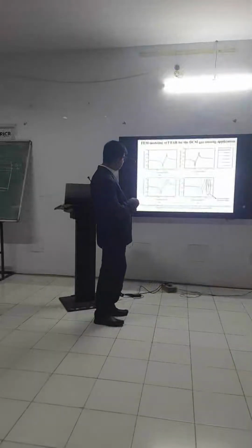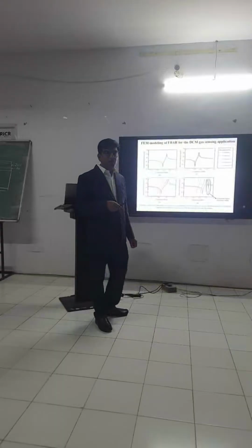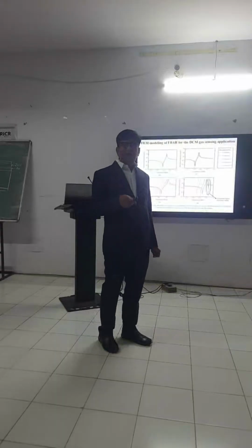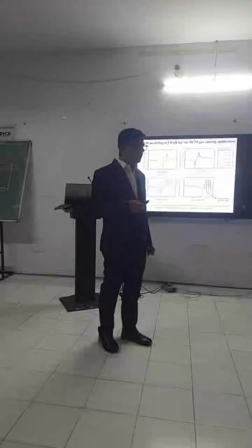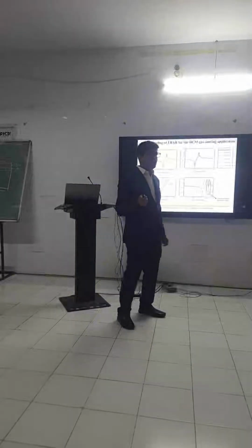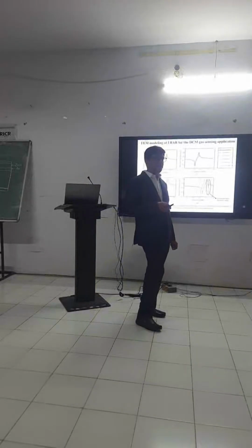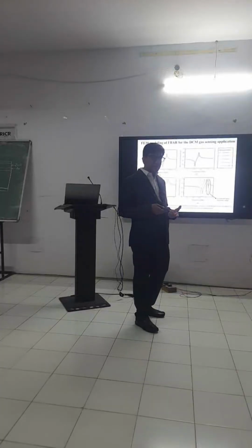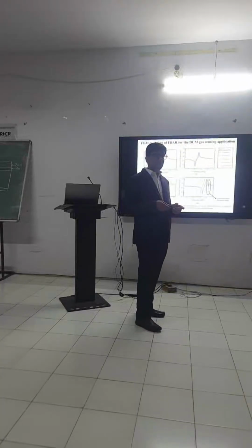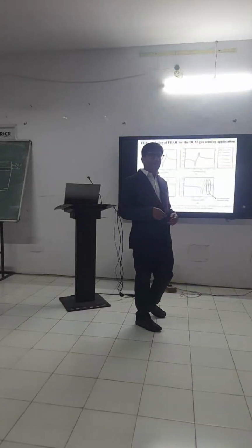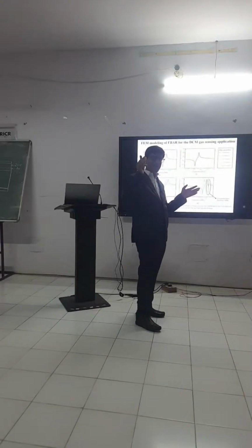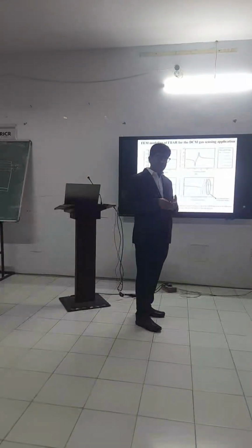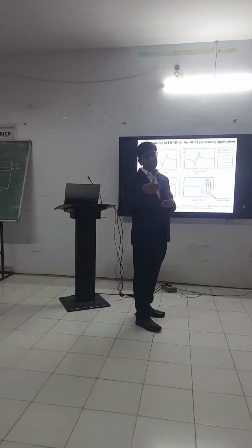Then here we can see how I have to optimize this sensing layer, because you can't randomly take 100 nanometer, 200 nanometer, 500 nanometer. So what you need to do is optimize the thickness and measure the performance. You can't directly enter into a fab lab and do so many iterations in fabrication. So before that you have to check your thickness with different combinations and check the performance.